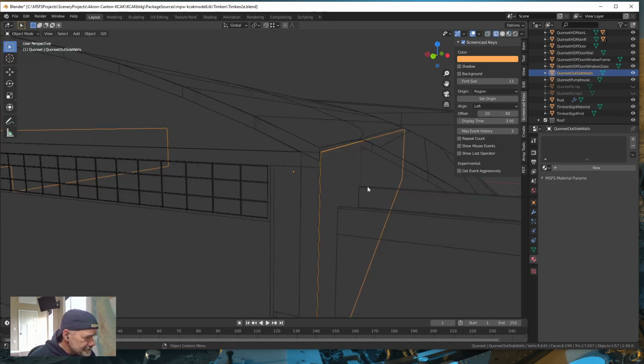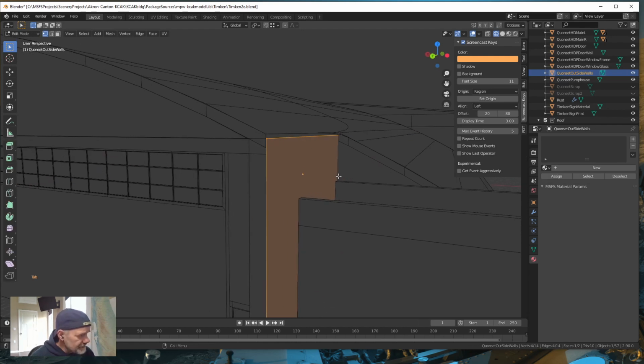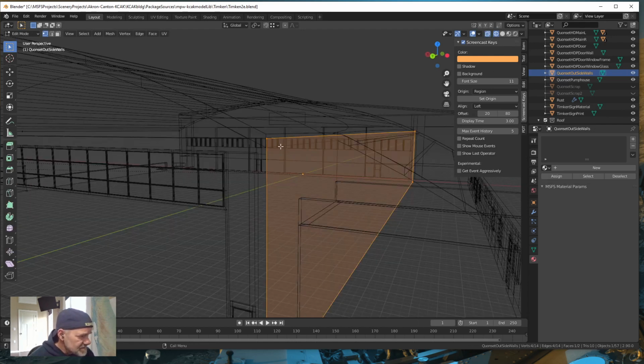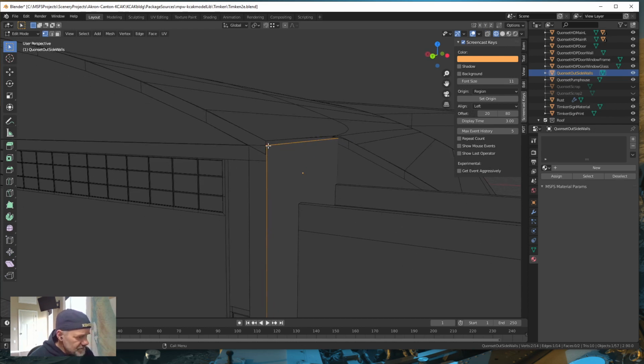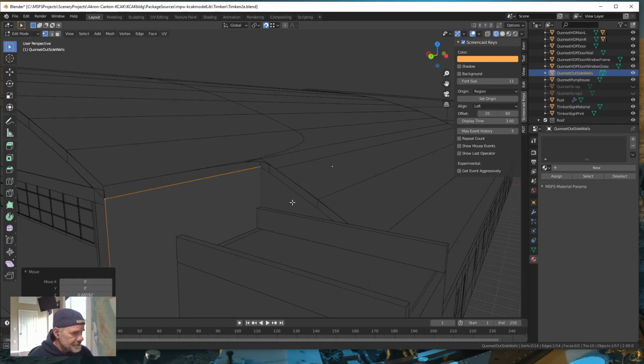And then I'm going to go into edit mode. Maybe. Yeah, edit mode. Alright. I can't see my vertices. There's 2 vertices. Now turn off wire mode. And we are going to move that down to this point right here. Alright, so we're going to move those, make sure that we have node select snap on. And we are going to GZ down to there.